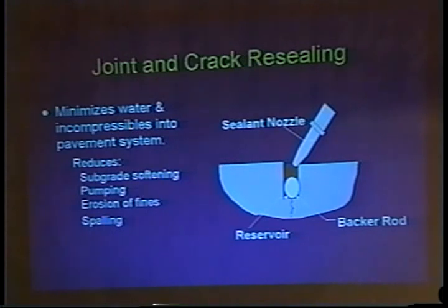But as we move towards plain concrete pavement nowadays with shorter joint spacing, what you're actually doing is taking that coefficient of expansion of your concrete materials and your aggregates, and you're distributing the contraction and the expansion over many more joints. So theoretically, you get less movement at each one of those joints than you would for the pavements which had longer joint spacing.